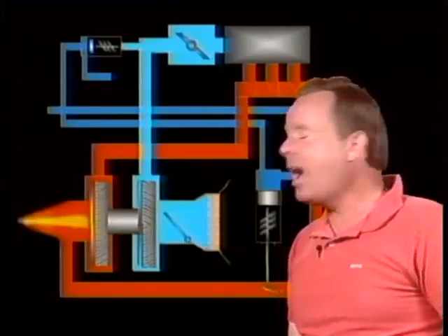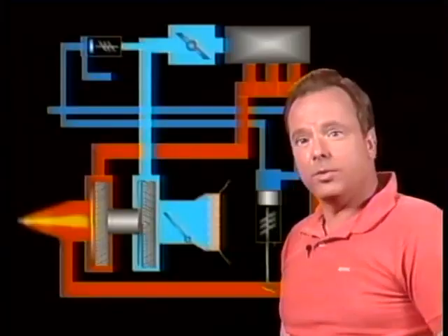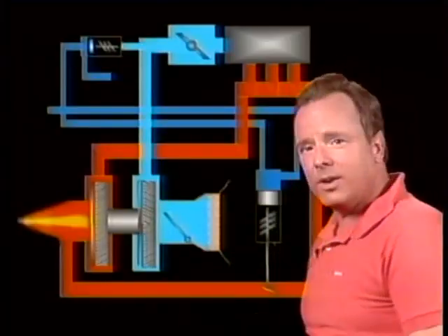They're going to ask you about switching from low to high impeller on the FAA written exam, and you're sitting on the ground, for instance, about ready to fly your Constellation, and you want to check to make sure that the supercharger is working right, so you shift gears in the supercharger. You shift from low to high impeller. Now, they're going to call this on the test a single-stage two-speed supercharger.